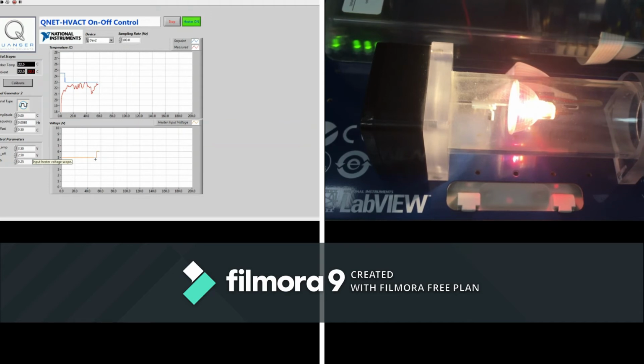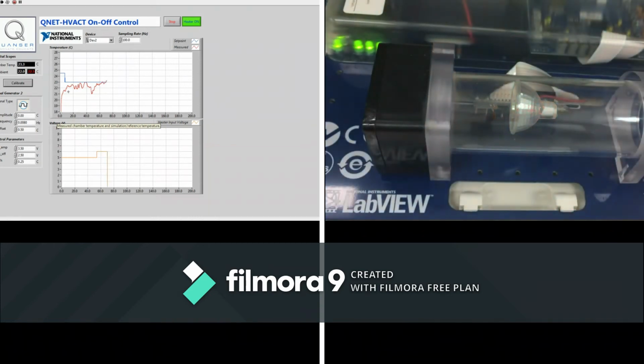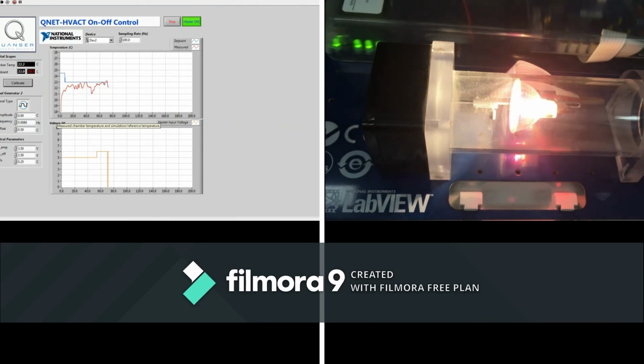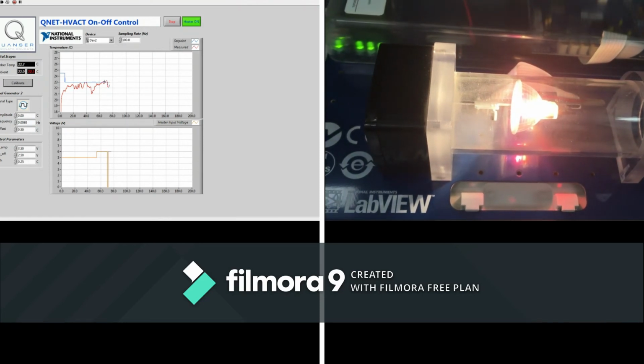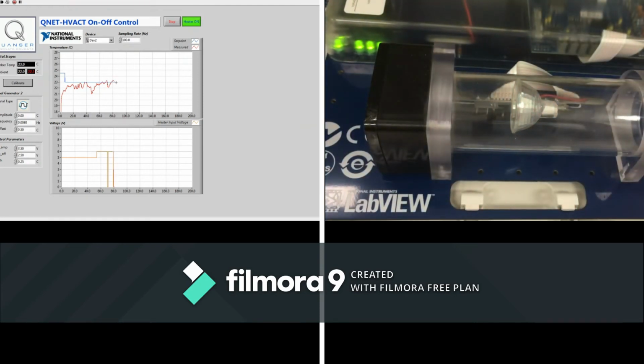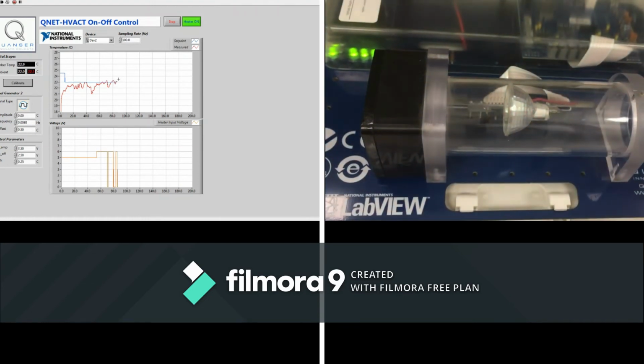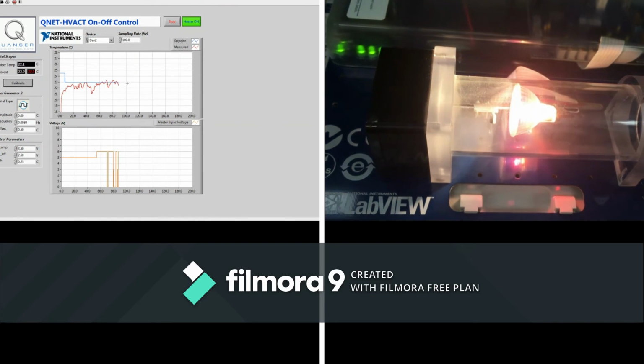We see that the voltage is increased right now, and the intensity of light and heat is also increased because of that. Now you see that we reach the set point faster compared to the small voltage. Since we reach this, the heater was on, and then again we need more temperature, so the heater will be fluctuating between on and off, but it will take more time while it was on because we already have our temperature.